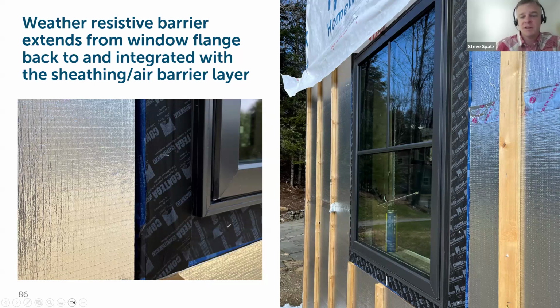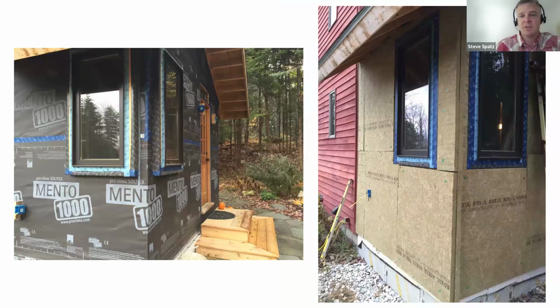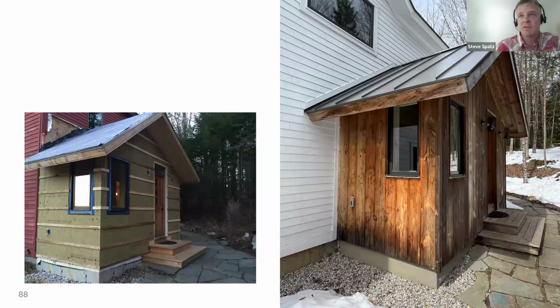The critical details here are the taping and the flashing to the WRB behind the insulation material. And so just here's an example of that in process. WRB, window bucks, taped back and flashed back to the WRB, the layer of continuous insulation installed, planing out with the window buck, strapping, and then exterior finish. Strapping does not need to be oriented vertically to create the effective break and capillary break and drying potential to the surfaces behind it.